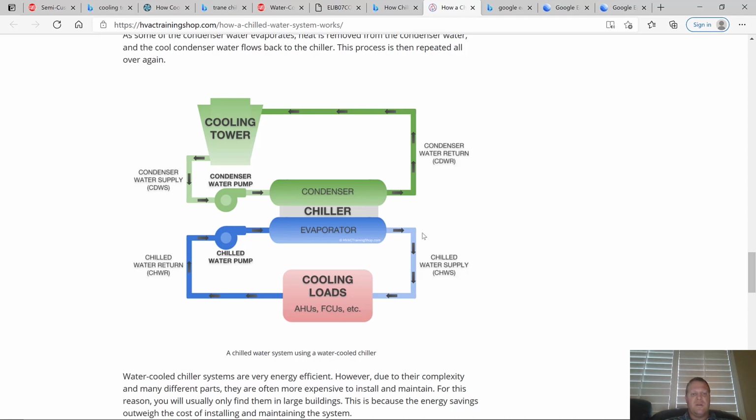to make that loop. So there's a loop here, and I would call this one a closed loop, as well as the refrigerant is closed loop, and this is an open loop because you're actually losing water through this process. So you're gonna have a makeup water somewhere to add more water into the system right here, so it's not closed.